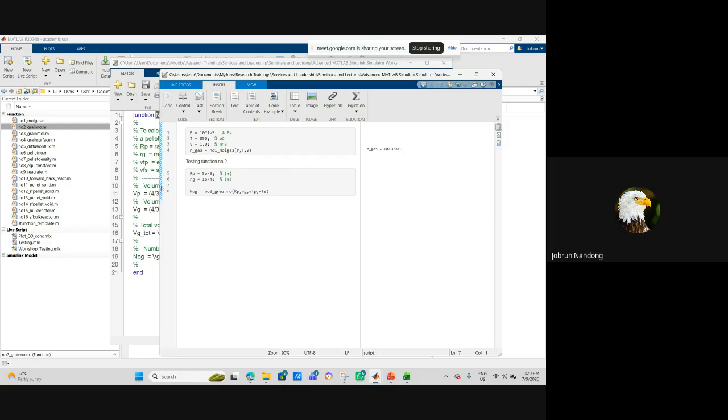Then let's say the voidage fraction for the pellet. Normally a pellet is very porous. So let's say we start with 0.4 there. 40% is empty. It could be more than that. There's no unit for this one. Then the fraction occupied by the solid material, let's say 30%, so that is 0.3, right? The remaining 0.3 is occupied by the oxide itself, the oxygen carrier material itself.